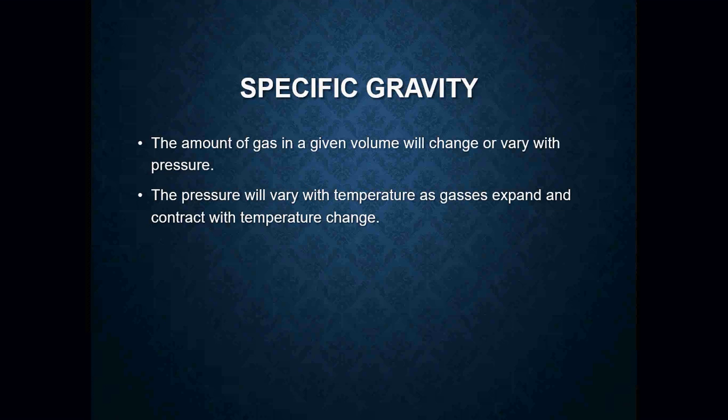And when that pressure rises, I have more pressure inside the gas line, which is why propane cylinders have relief valves on them. Those relief valves are meant to open in the event that the pressure inside the cylinder gets too high. It's going to release some of that pressure. Every once in a while, maybe in the dead of summer, people that have propane tanks may smell a little bit of propane coming out. That's normal. That's those relief valves working. That's actually a good thing.